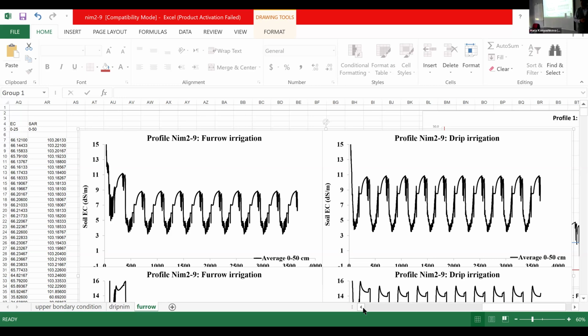Okay, I think there's one question. Yeah, this one. So, unless you fit observations during the 10 years period, after the first year, the simulations are not really useful because they will be the same. Yes. We just evaluated to see what will happen in 10 years. And there is another option, because here we just put the data set for 1 year. If we have the whole data set for 10 years, we can put all of them into the model as a variable boundary condition, and definitely we would have different results.